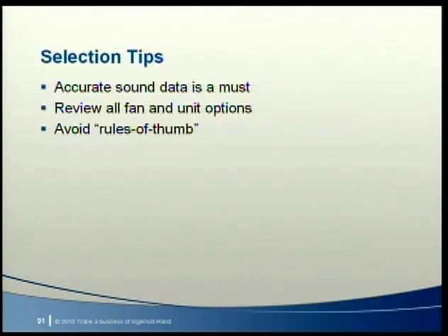In summary, remember the following 3 points when selecting and comparing quiet fans. Sound data taken in accordance with ASHRAE Standard 260 provides the best indication of sound produced by the entire unit. Selection programs allow you to compare all fan and unit options. And finally, avoid rules of thumb. Octave-band sound data is needed to determine which fan is the quietest.